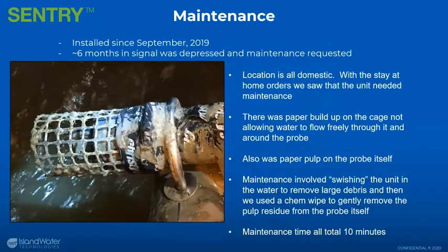So right at the beginning of COVID-19, we ran into a little bit of an issue. Again, I mentioned that this location is completely domestic wastewater. And so with the stay-at-home orders, we saw a difference in the sensor data. So we went out to the site and we saw that there was quite a bit of paper buildup and residual fibers all over the outside of that cage.